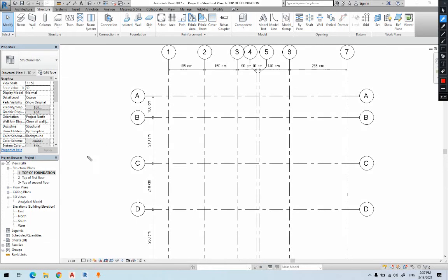So this is why it's important. You have 3 levels. If you are here, you will draw the columns to the top. If you are at any of the levels, I recommend, for example, the 2, it doesn't matter, because even if you are here, you will draw it twice. If you are at the top, you will draw the columns down. This is 2-way in Revit: we can draw things up and down. So we're going to explain this to see what it means. It's up to you, but you have to remember, wherever you are, you need to know which plan is active, because when we're drawing the column, it's important to specify the direction of the drawing.